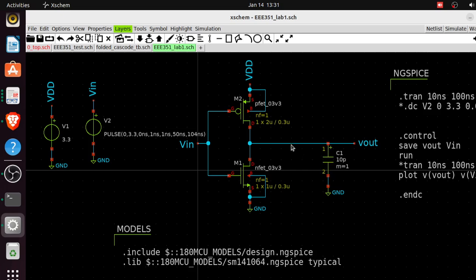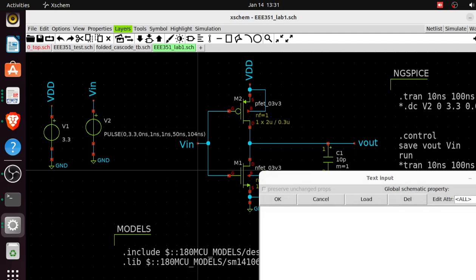So it means if you make this your CMOS inverter and you try to load it with another gate, maybe another inverter, and if the input capacitance of that gate is about 10 picofarad, you will not be getting a good result. It will load it, it will have a bad effect. Let me just do a proof that okay, it's the capacitor that is affecting it.